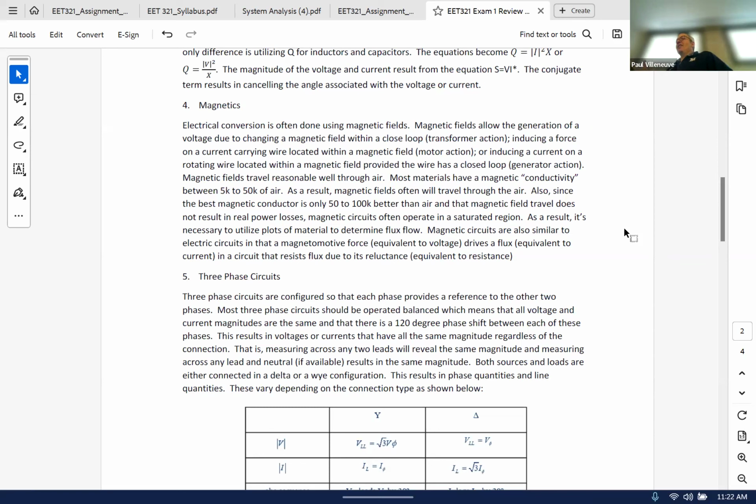I mean, that's the definition of an air gap, right? There's no air between the two, which means they're touching each other. That's called rubbing, and it wouldn't last very long. So you have to have an air gap to allow rotation of the rotating part relative to the stationary part. So we have to understand the concept of permeability of materials.